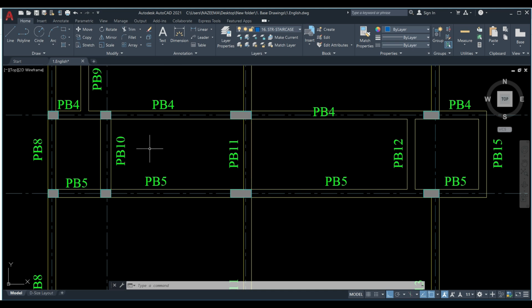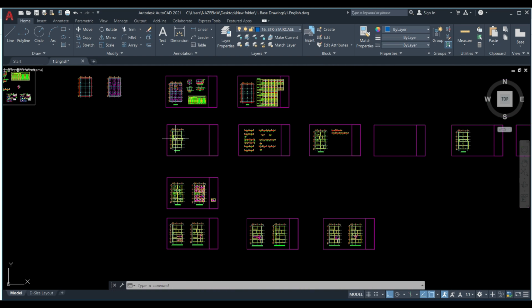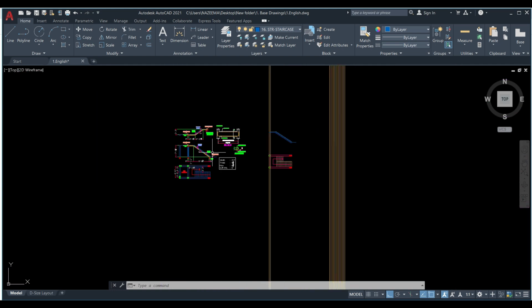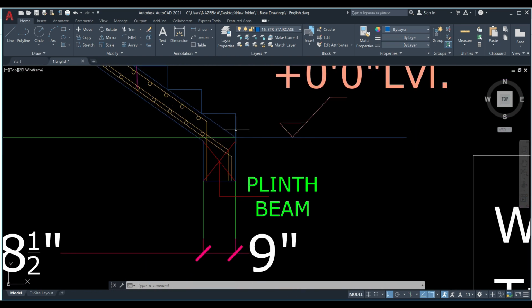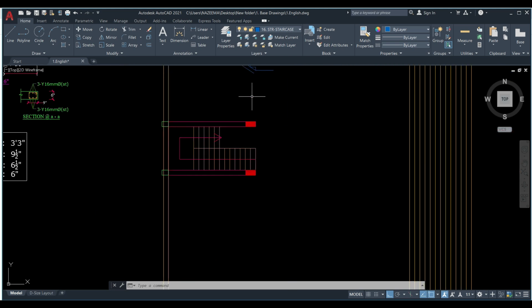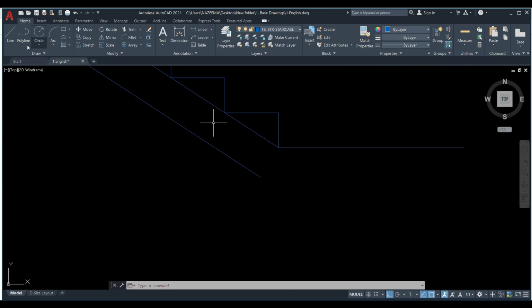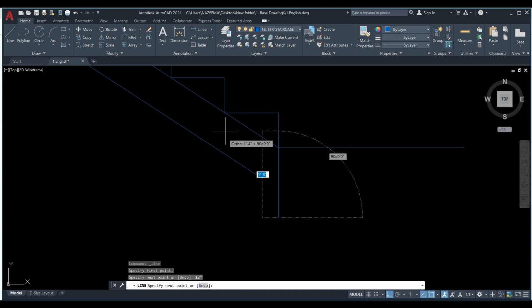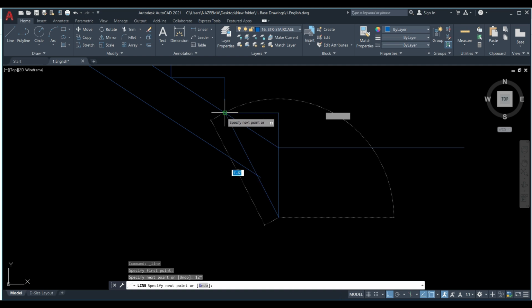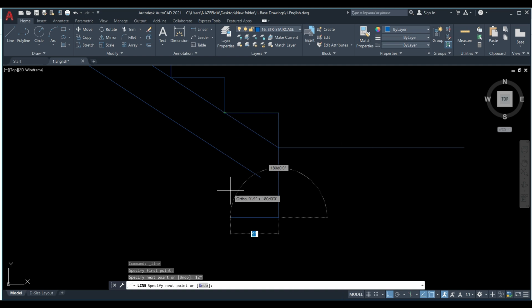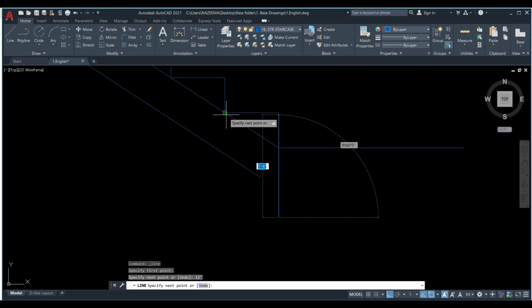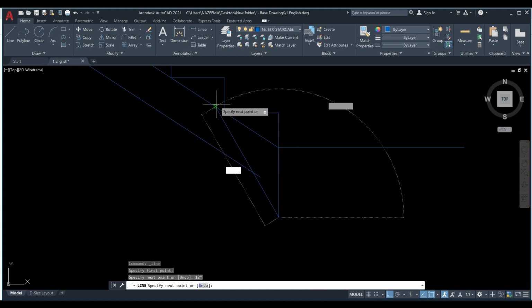Okay, so this is my staircase, this is my left portion. I have got a beam over there. So for that beam, how will I draw it? If you just come and refer to this, the moment my staircase ends, the beam part starts. Okay, so from this very line, I'll mark 12 inches like this. Then I'll go forward until this staircase, until this step. It's actually 9 inches, but on the side you can make a tiny adjustment, no problem. Okay, just go till there.